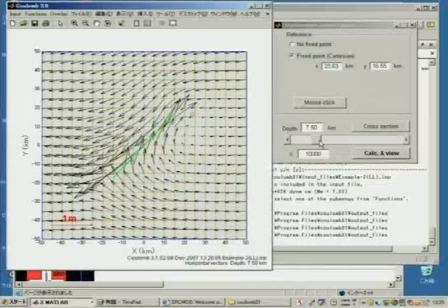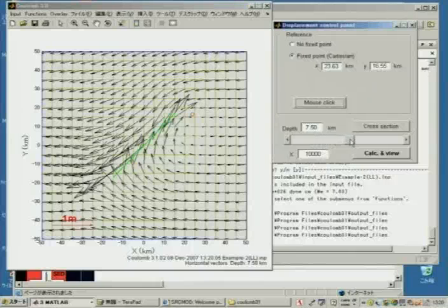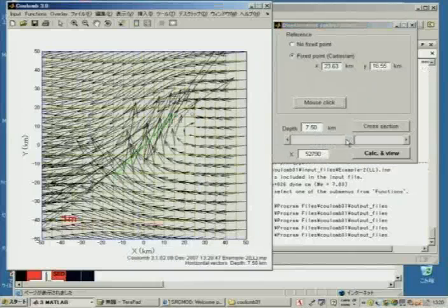Now, I want to introduce to you the other part of the displacement control panel, and see how it has a number down there, 10,000? That number has a meaning, which means you can see what 10 kilometers is on this map, and that 1 meter of displacement is exaggerated 10,000 times. So it has a very specific meaning. It's not a relative term. But why don't you just use the slider and slide it so you change that, or make it really small.